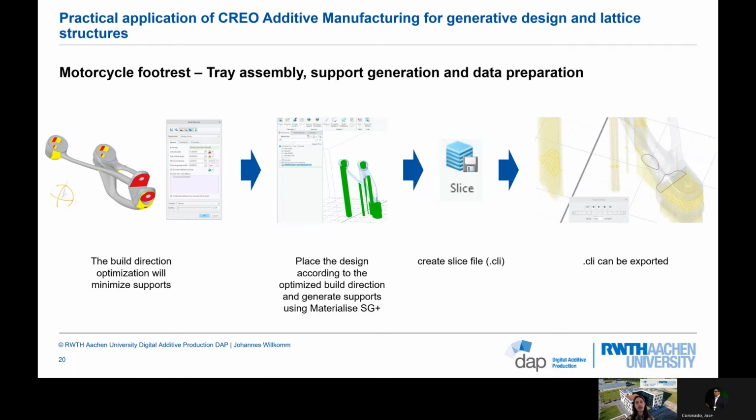It is available to the design and manufacturing engineer early in the process to evaluate the impact of a design decision in the context of additive manufacturing. So as I said, orientation is quite important regarding the design restrictions, and so I have the benefit to define that in an early state.